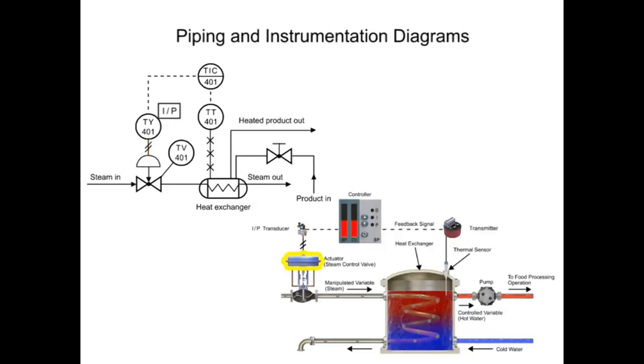The pneumatic-controlled diaphragm actuator that opens and closes the globe valve regulates steam in the process. The actuator is represented by the half circle in the P and ID. The arrow pointing downwards from the actuator indicates a fail-closed valve type.